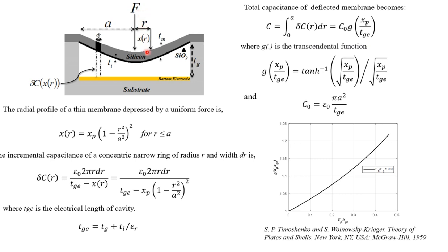Yeah. So in order to calculate the capacitance, because of the profile, you see it's not a parallel plate capacitor. Okay, there's a bottom electrode and the top electrode is silicon itself, which conducts when it is biased at a certain static voltage. So what happens is, owing to the establishment of the electric field, since it cannot move at the post where it is bonded, it does create a static profile like this.